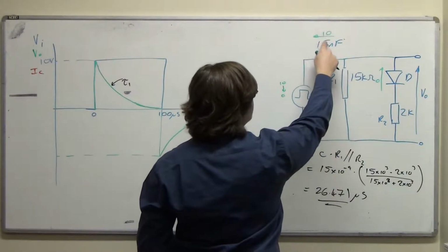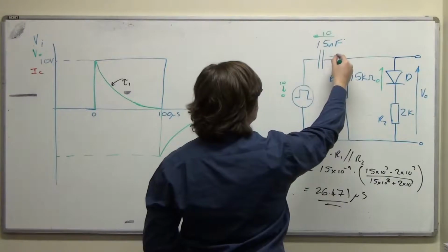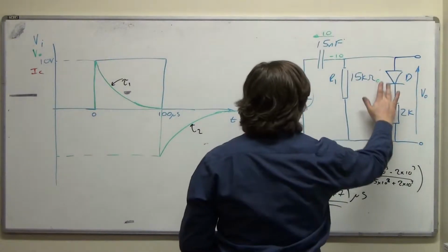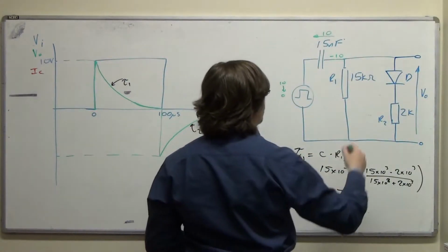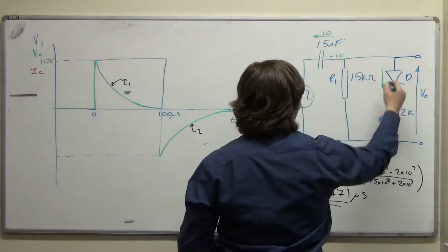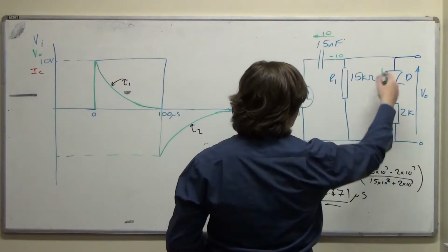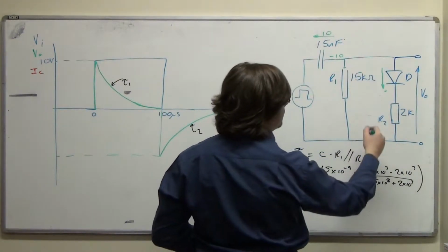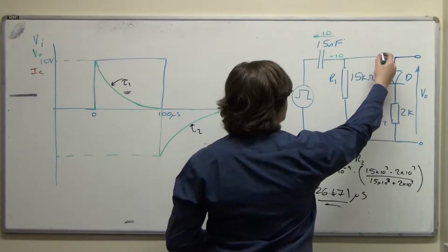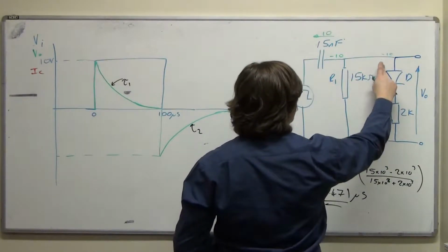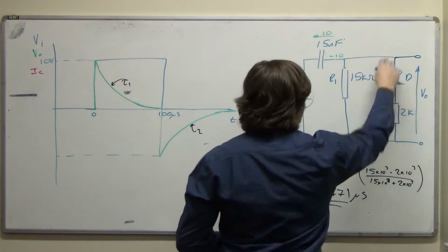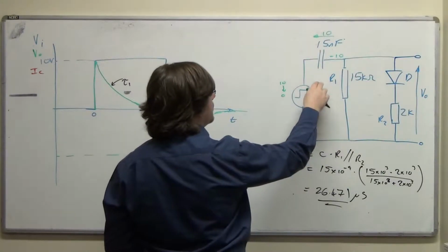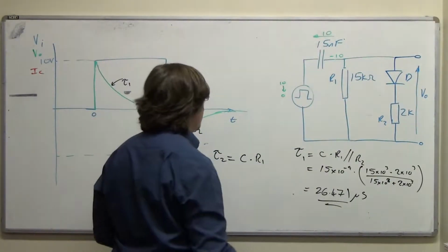Now that's not to say the capacitor has no voltage on it, it's to say that this has to become -10. So if that's -10, then the diode is biased in that direction, where, assuming it's switched off, we've got 0 on this side because there's no current flow, and we've got -10 up here, so it's reverse biased by -10 volts, no danger of conduction. This branch has nothing to do with anything anymore, and we're down to a regular high pass RC network of 15 nanofarads and 15 kiloohms.